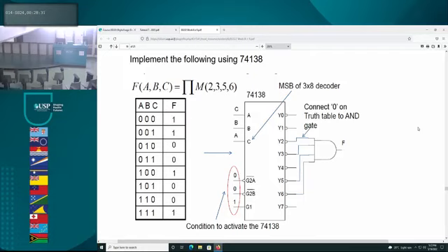Right? So what do we have here? So if you look at it, we take all the addresses where the zeros occur, okay, and you AND it. You AND all the zeros, right? So there were 4 zeros, and we AND those 4 zeros. Okay, so you can go through this truth table.